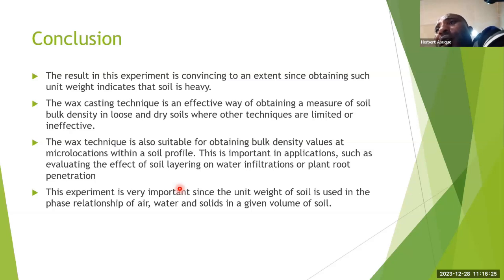If it is not well settled, the load will compact it, and since the load is rigid, that may lead to cracking. That is movement that is not well controlled. So it has to be controlled before the load is put on top, so that it will not cause uncontrolled movement, which may not be even, and some parts go down while some are still floating. Then it will be cracking.